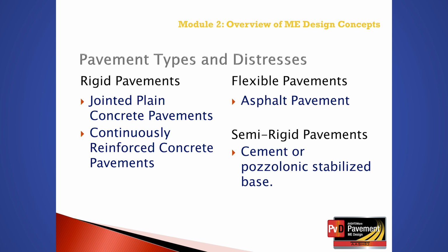For flexible pavements, asphalt pavements consisting of conventional asphalt with the thicker aggregate base layers, deep strength asphalt pavements with thicker asphalt layers relative to the aggregate base layers, and full depth asphalt pavements are appropriate design strategies.